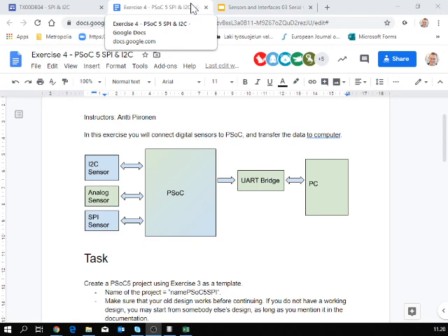And then yesterday you had this analog sensor. Today you will add an I2C sensor. That's also a temperature sensor. That's the one. TC74, I think. You have better eyes than I do. Right. Read if it says TC74, please. Somewhere on the can it should say TC74. Okay. That connects into the PSoC on the I2C module.